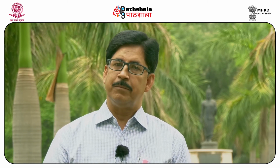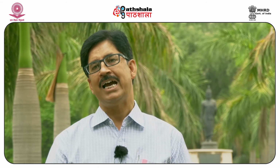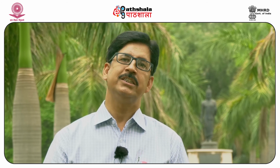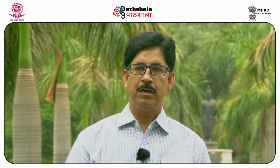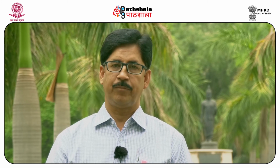It is better to work in the synclinal zone because there you will find much stronger rock as compared to the anticlinal zone, where you will have added fracture systems because of tensile stresses. But you have to see in what way the groundwater is moving through those rocks, and groundwater seepage has to be checked.